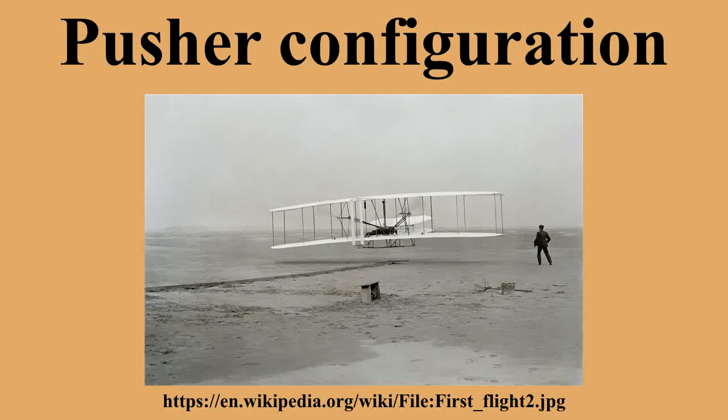The so-called push-pull layout, combining the tractor and pusher configurations, that is, with one or more propellers facing forward and one or more others facing back, was another idea that continues to be used from time to time as a means of reducing the asymmetric effects of an outboard engine failure, such as on the Farman F.222, but at the cost of a severely reduced efficiency on the rear propellers, which were often smaller and attached to lower-powered engines as a result.